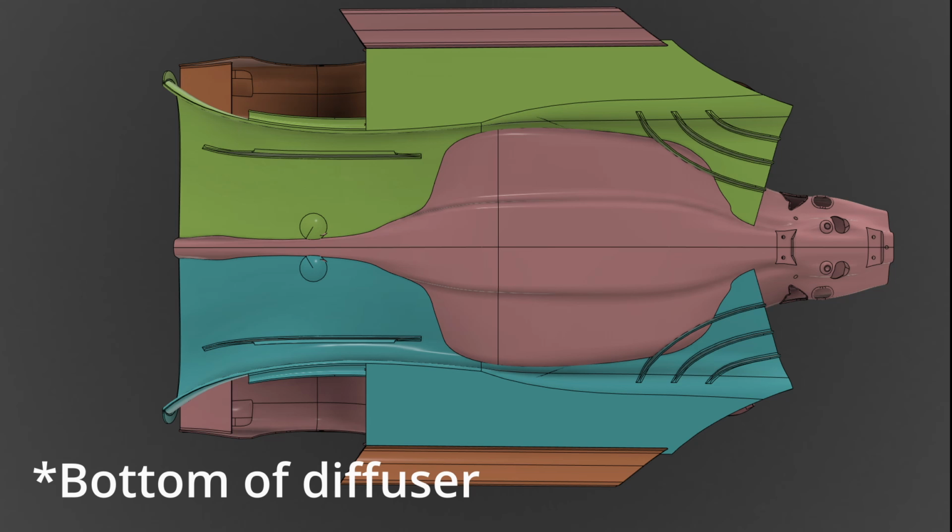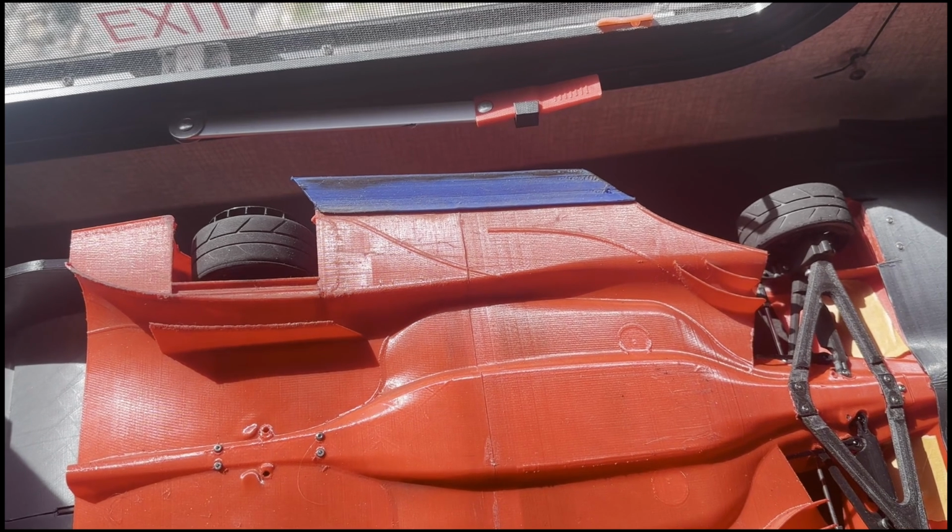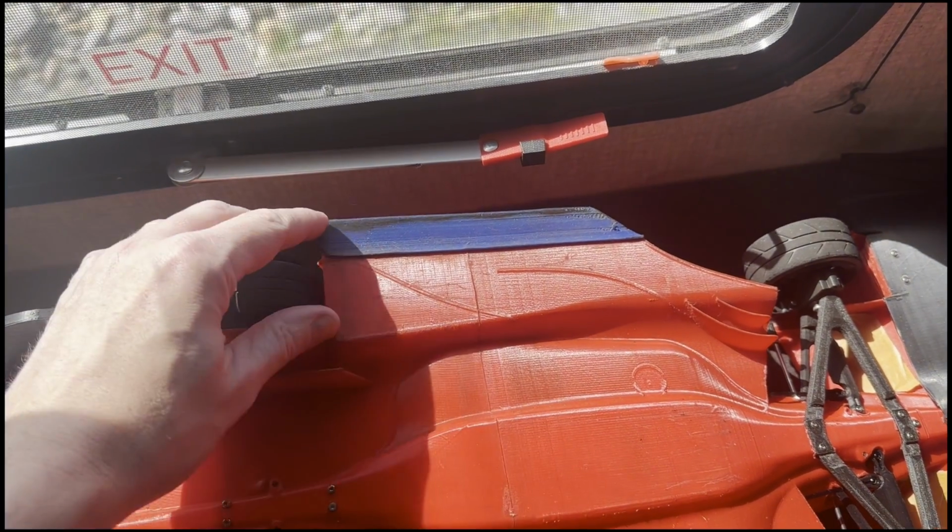This is a view looking at the top of the diffuser profile, and you can see the diffuser's horizontal expansion, meaning we can actually make the diffuser narrower at the throat widthwise and then wider at the outlet. This is the best thing for diffusers because horizontal expansion is not ride height sensitive. Most race cars have a limited amount of horizontal expansion because of rules or because of physical packaging between the tires themselves. So running on the edges of the floor here have some really important aero devices, which are these